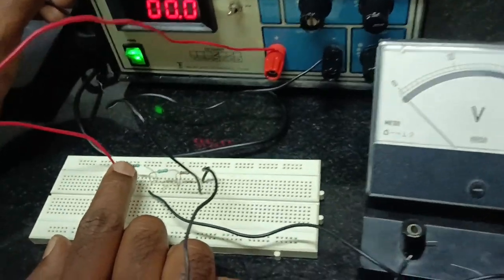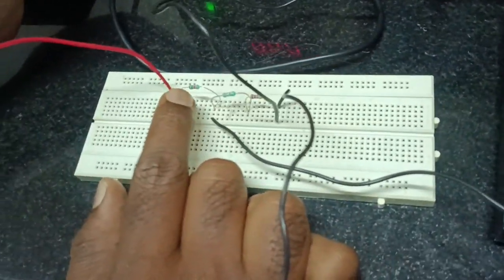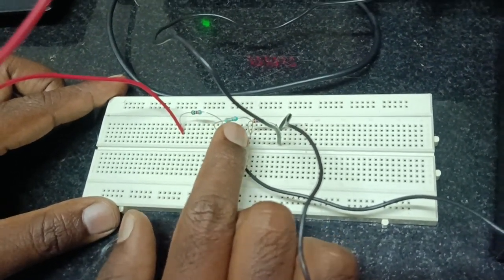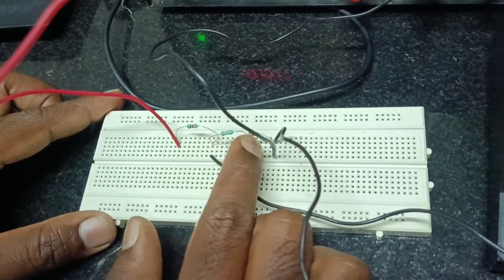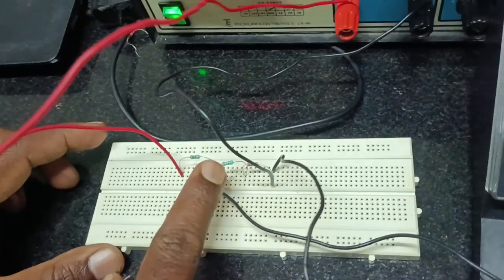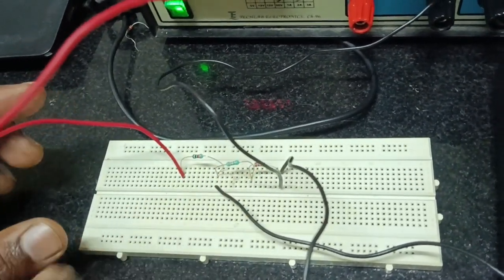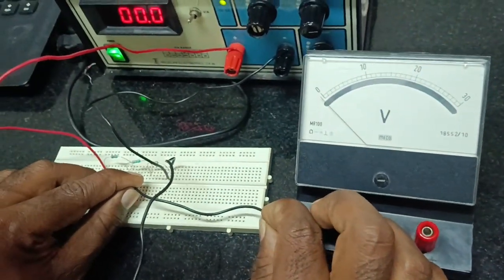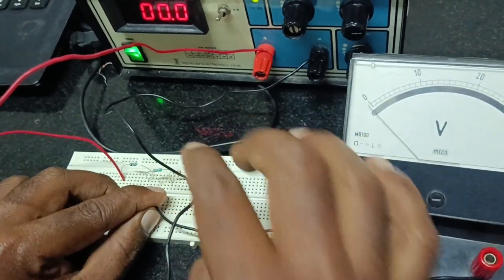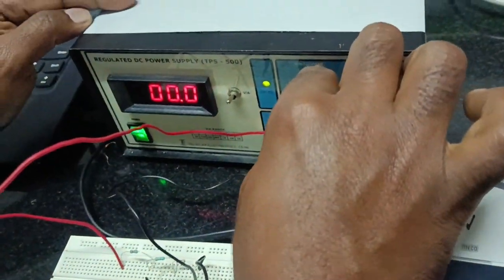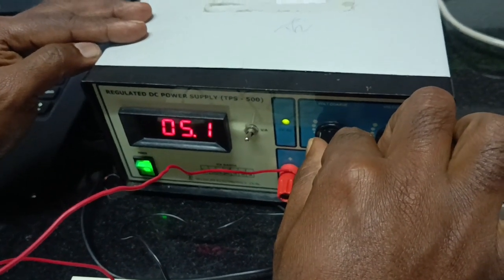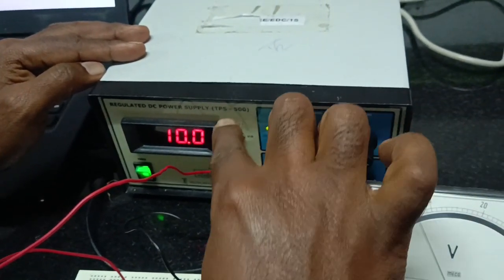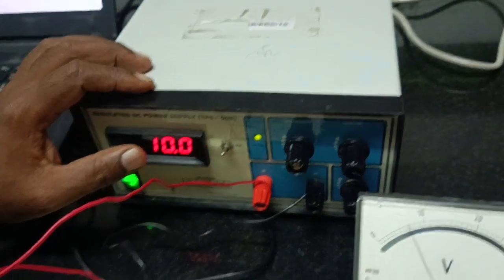So this is the circuit diagram to find out the VTH value for the 1 kilo ohm, 2.2 kilo ohm, then the 3.3 kilo ohm as well as 2.7 kilo ohm. As per the circuit diagram connection, we connected here and we can use the voltmeter across the 1 kilo ohm as well as the corresponding ground. Now we are gradually increasing the voltage level in the RPS. Now fix the voltage at 10 volts. So this is the 10 volts we are giving as the input voltage source.